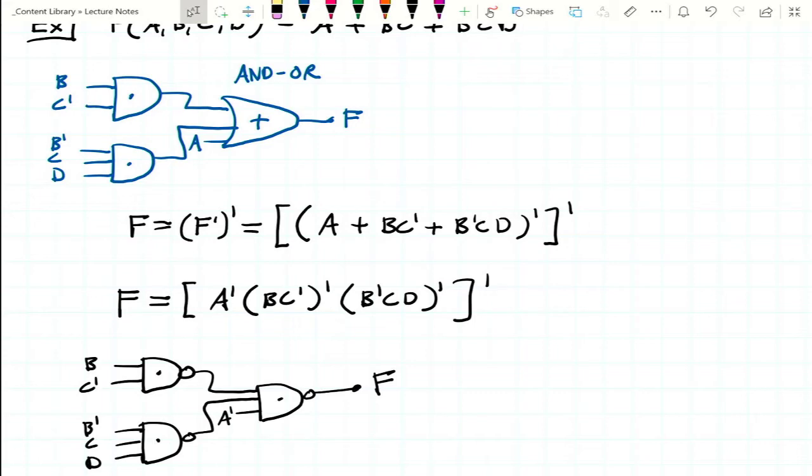Because of the way De Morgan's theorem shakes out, right? The OR operation that happens here under De Morgan's theorem becomes an AND operation, because we inverted it twice. That external AND operation got inverted. So that lets us convert everything to NAND gates. And the reason why is it's faster and more cost effective. Are we using the involution law at the second one? Is that why we didn't fully apply De Morgan's law to B and C?